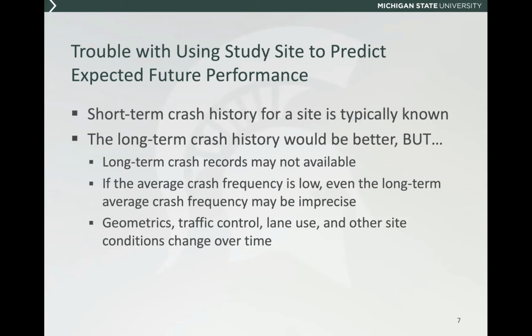So generally, road agencies would have very good asset management inventory databases for whatever the current status is of the road network. But if we ask for a similar snapshot 3 years ago or 5 years ago, we would tend to have less reliability there. And as an example, here in Michigan, the DOT has basically retired its prior sufficiency file that maintained a lot of this inventory information. And so now if we try to make comparisons over time, these roadways have been segmented in a different manner, and it's not a simple apples to apples comparison. And so these are a few of the types of issues that become problematic over long time periods.